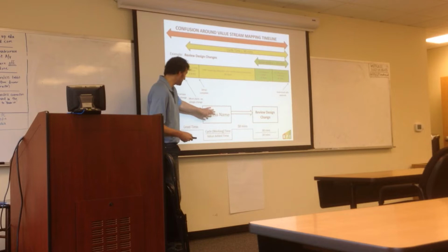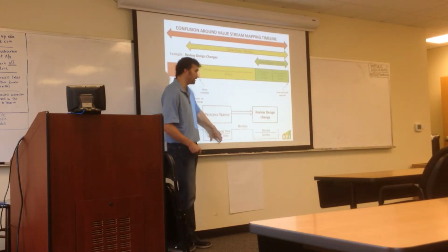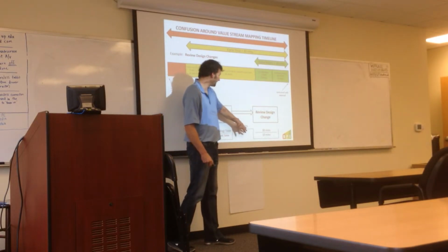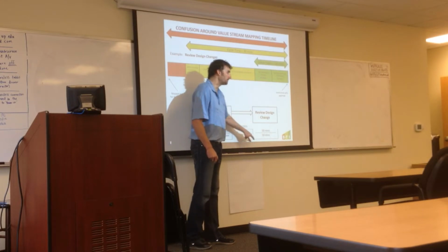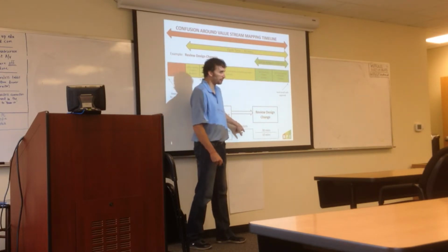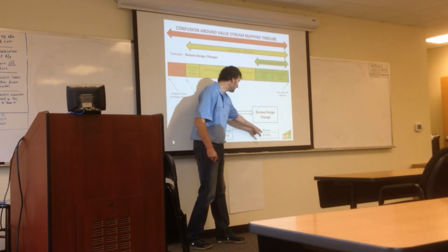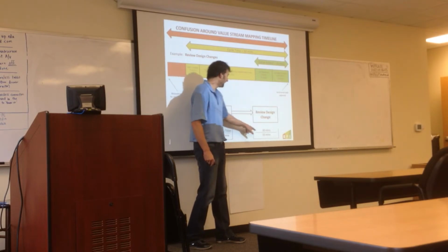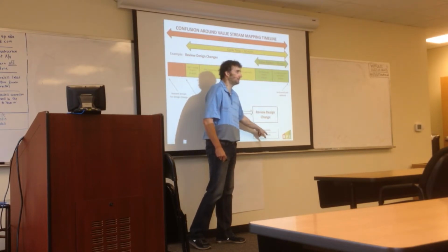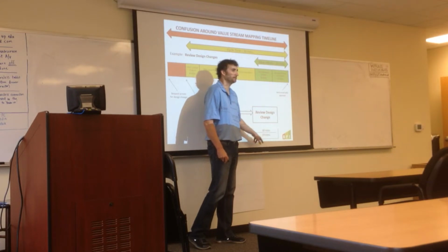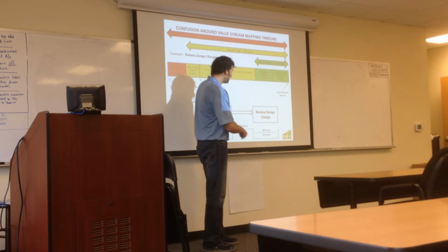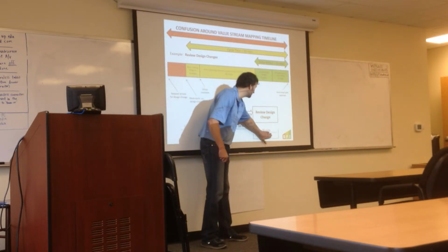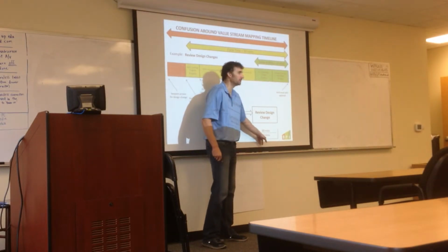So that's a process. We have a lead time and a cycle time or a value added time, depending on how detailed you got. And so you might have something like 38 minutes there, 30 minutes of actual time, so it waits 8 minutes prior to that process basically because there's a gap of about 8 minutes between there. And 10 minutes of that 30 minutes is actually value added, so there's 20 minutes of non-value added time, or whatever you call wasteful time in there. So that's sometimes how I see it written, but often this isn't available, so we just have 38 and 30 in the bottom.